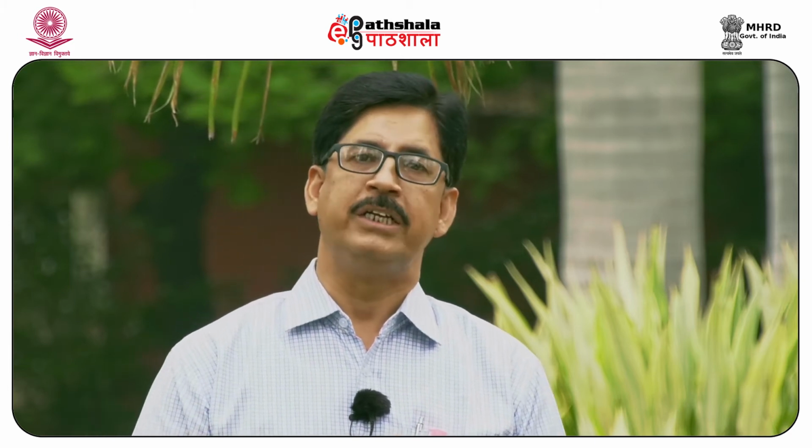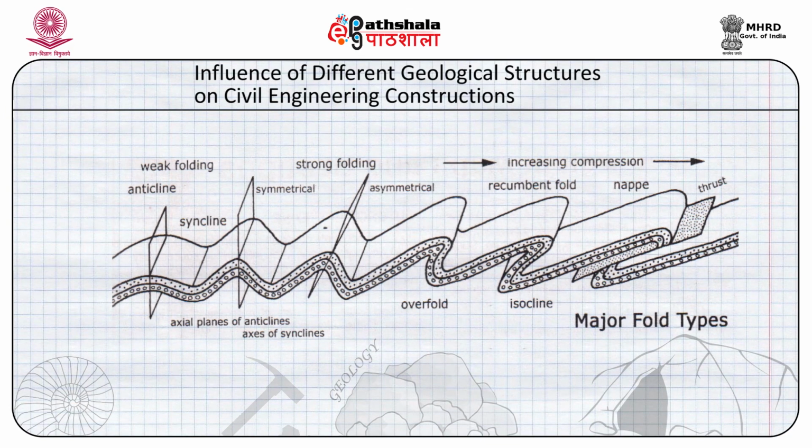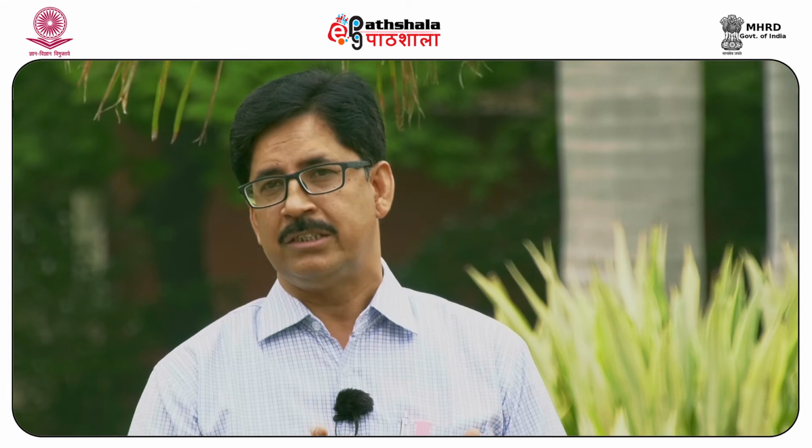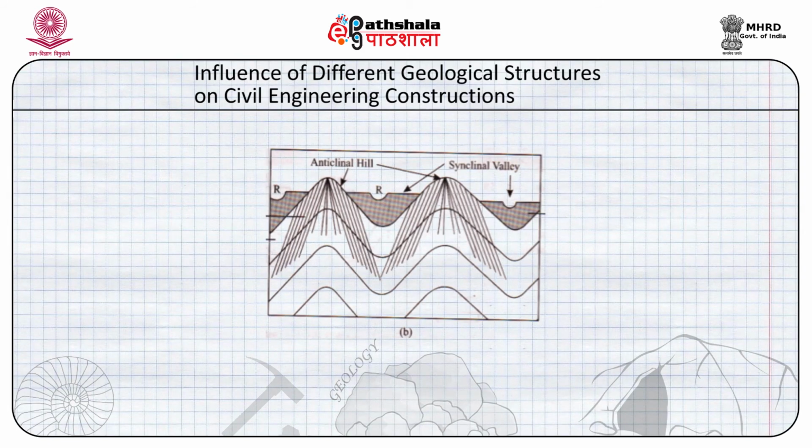Now, when we have folding, we may have repetition of rocks. Again, the same rocks, strong or weak, may keep coming after some distance below your structures or along your structures. In folding, when we have anticlinal zones, normally we have tensile stresses along them. The presence of tensile stresses along the anticlinal zones will result in the formation of a lot of fracture systems.